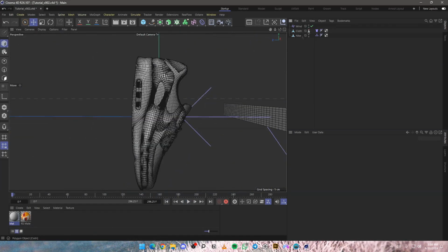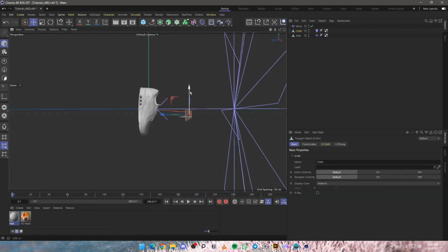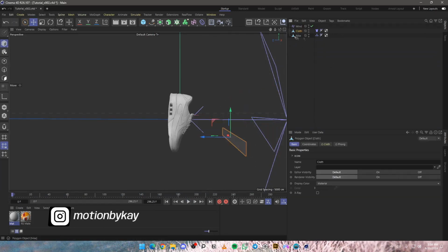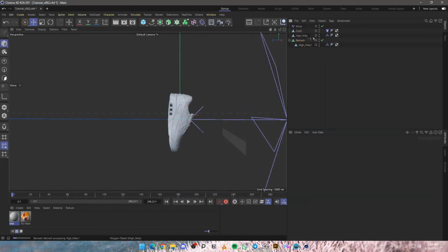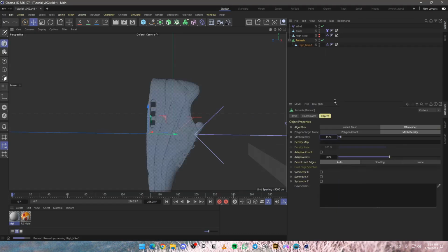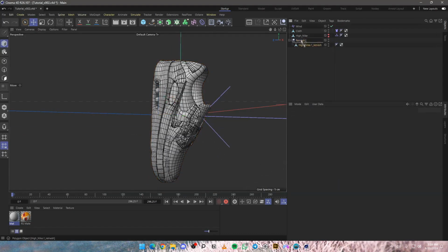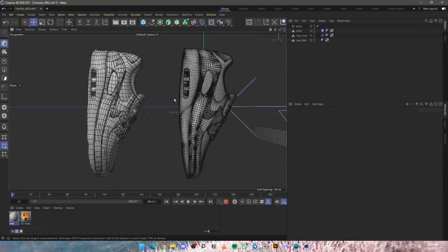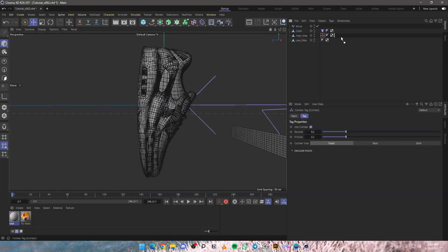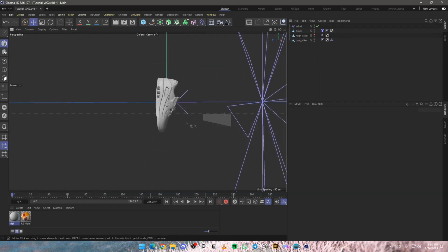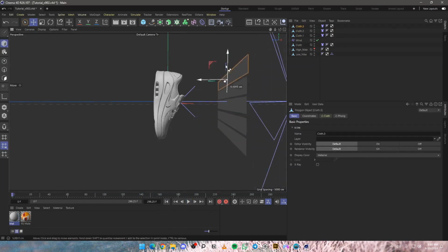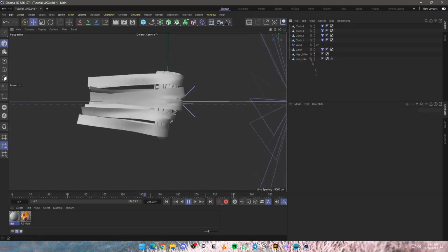Because I used the high poly version of the Nike shoe, there's some slow performance in the viewport, and here I just added a few more planes to show you guys. To fix that, I created another version which had less polygons. So the next thing you should do is to add the cloth collider to the low poly version and have the high poly version visible. Okay, here we're just checking the performance of the viewport, which is much better than before.